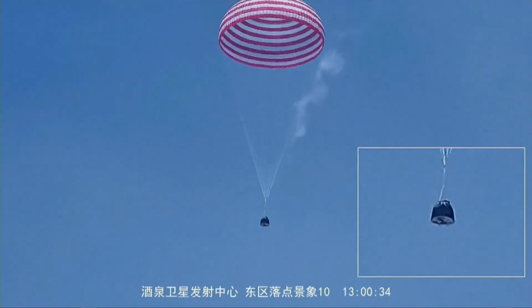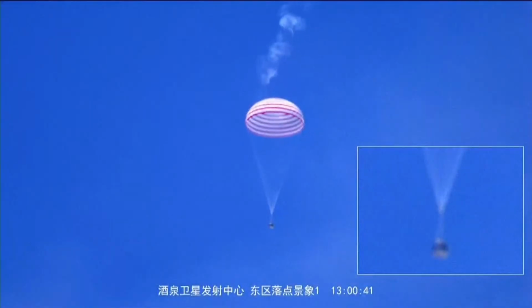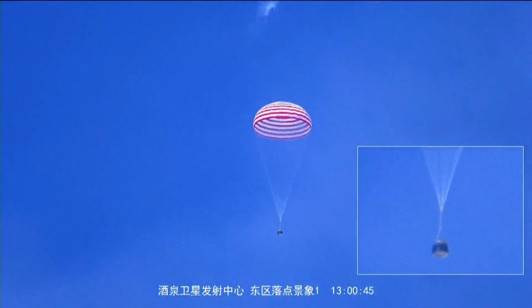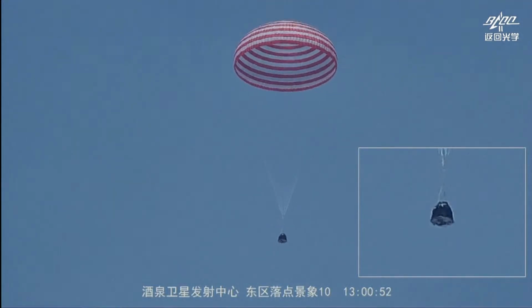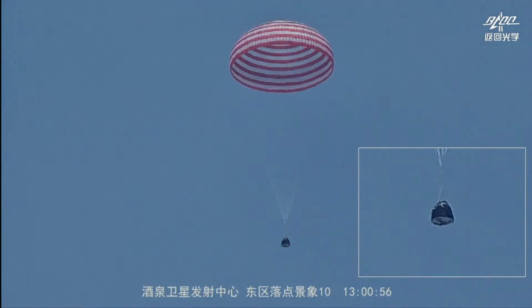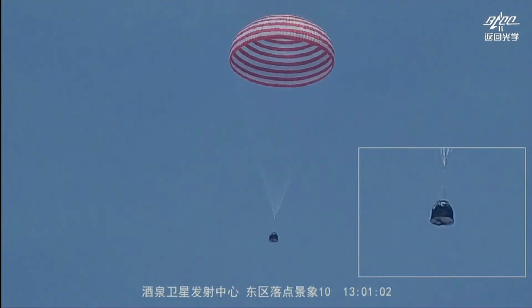You see that, as I mentioned, it is a controlled re-entry. So as Professor Zhang mentioned, we can control the attitude of the capsule during the re-entry. This is the function of the propulsion system on board the re-entry capsule, but it only changes the direction in the roll direction, to change the direction of the lift. With the change of the lift, we can change the trajectory to the landing point.